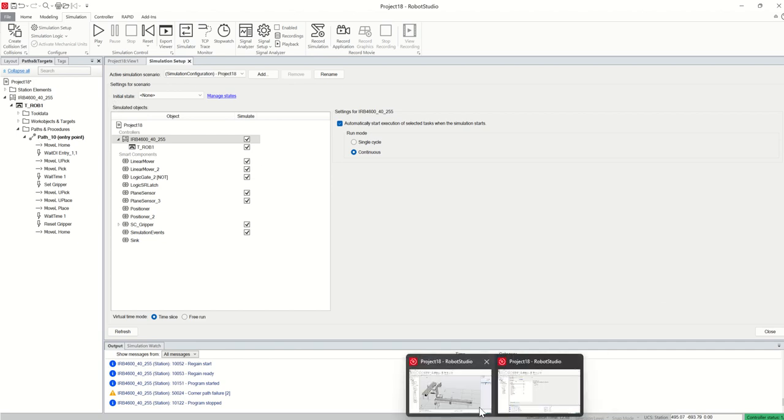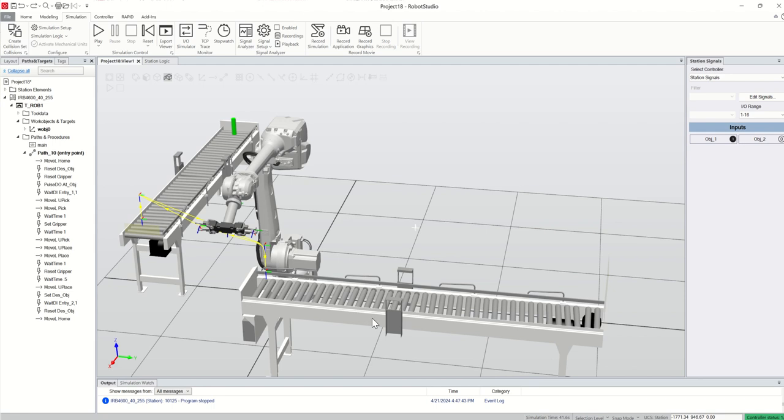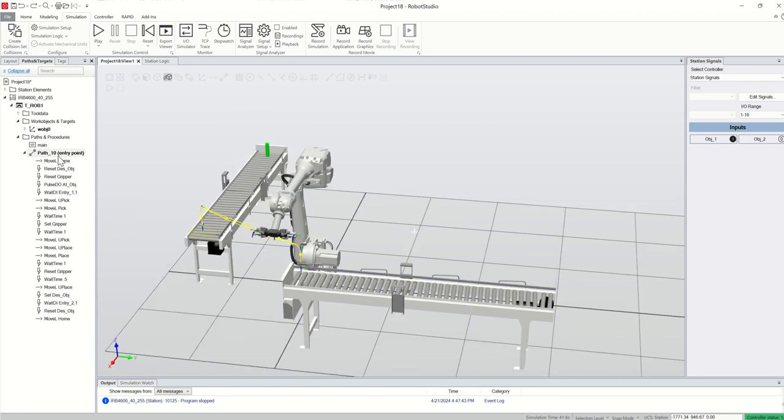And if I bring back the other one, like this one, then you will see here I needed to bring a lot of other instructions. For example, after the move home position, I needed to bring back reset destination object, reset gripper, pass object, wait until wait digital input until entry 1, and so on and so forth. So you can really follow this step to get at least the station side.